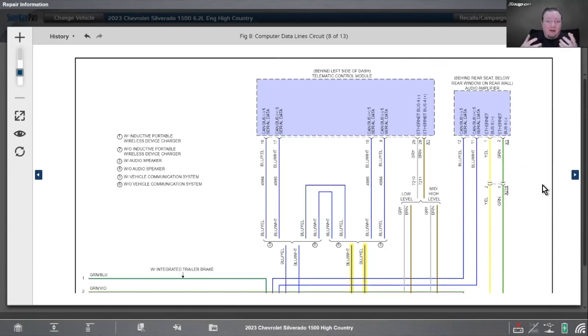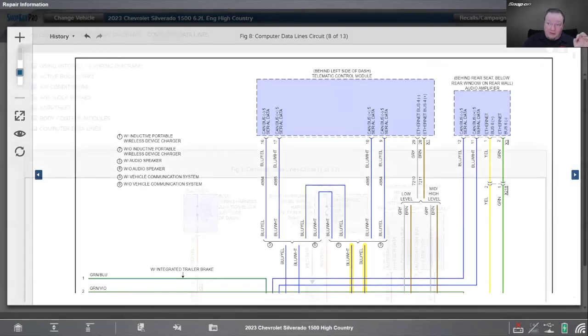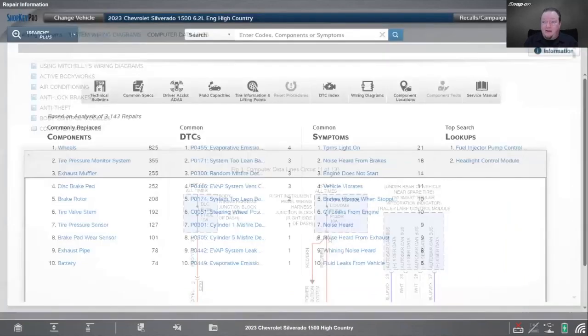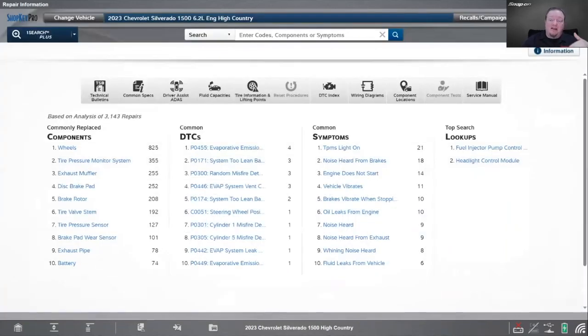So within these vehicles, they're very complex. It's just a whole mess of wires everywhere. Ethernet, CAN bus, multiple buses. As I said, once CAN bus gets too many modules on it, you get data collisions and backups. So that's why they started going out into multiple buses. They also went into Ethernet, CAN FD, all these faster technologies inside the vehicle, not communicating with the scan tool. So sometimes if it's a really complicated network problem, you may have to get into the module itself, past the gateway module, in order to diagnose.